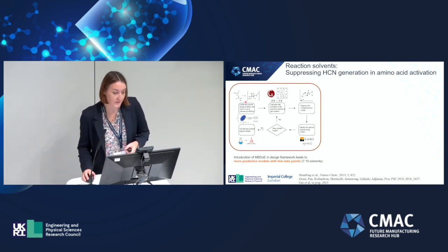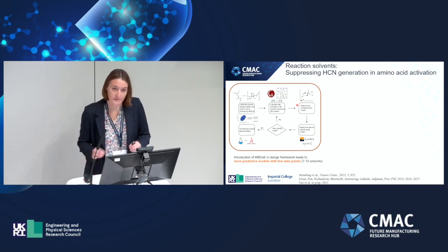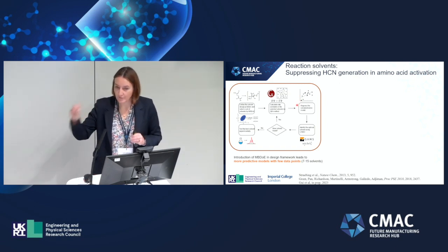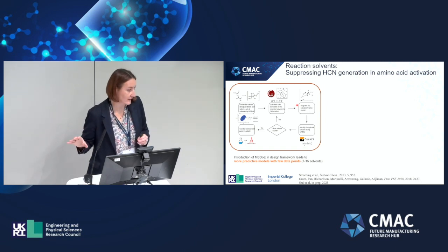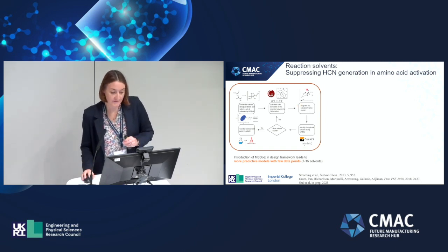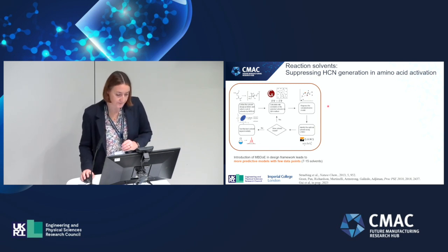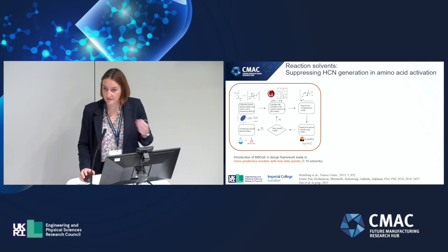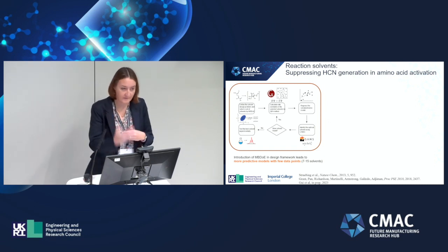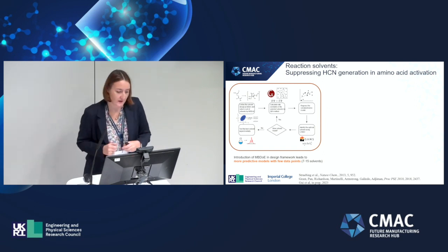So we start with a small set of solvents. We do a few QM calculations to predict the rate constant in those solvents. And then we build a surrogate model that enables us to predict what will happen in other solvents for which we have not done QM calculations. We then use this model, which is actually a multilinear model, so it's a very simple model, in a computer-aided molecular design framework, and that enables us to identify the best solvent or a set of best solvents.